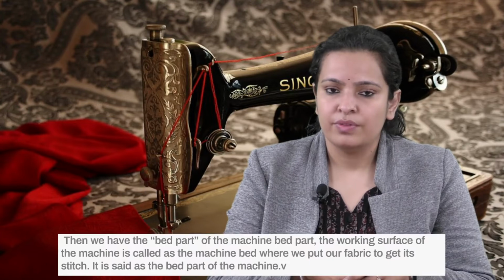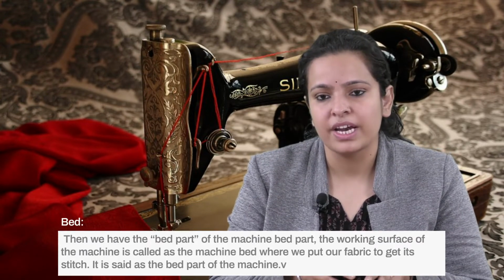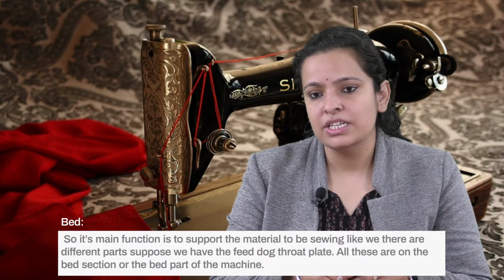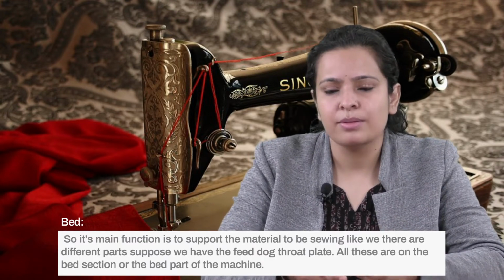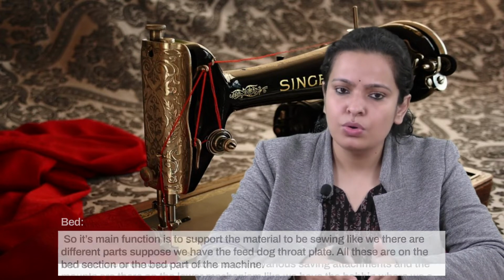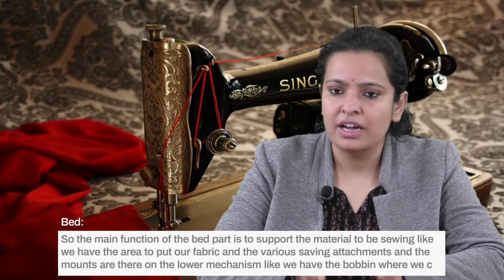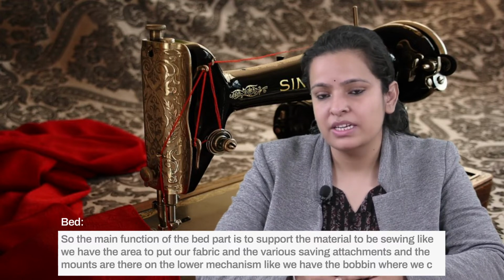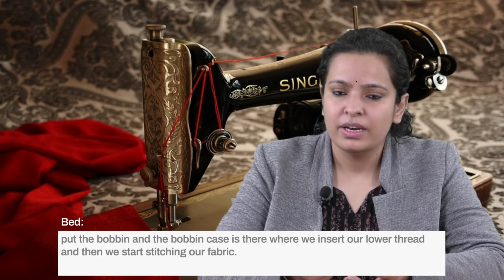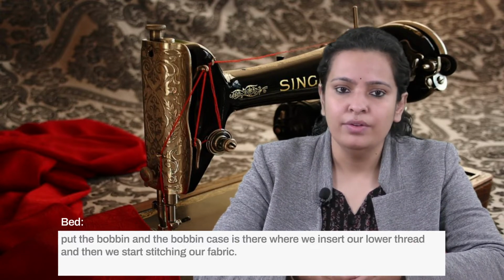Then we have the bed part of the machine. The working surface of the machine is called the machine bed, where we put our fabric to get it stitched. Its main function is to support the material to be sewn. There are different parts, like the feed dog and throat plate. All these are on the bed part of the machine. We have the area to put our fabric and the various sewing attachments and mounts on the lower mechanism. Like we have the bobbin, and the bobbin case is there where we insert our lower thread and then we start stitching our fabric.